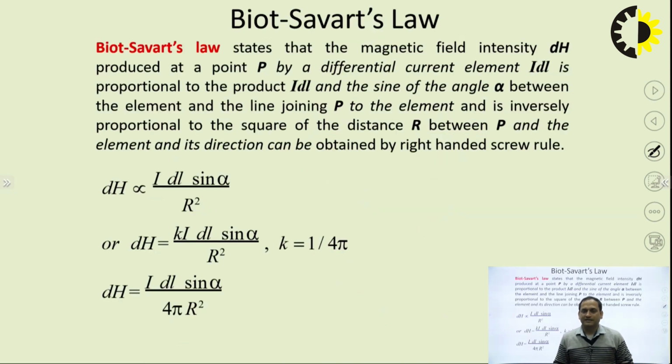Okay, so now let's start unit 3 in an efficient manner so that you can understand the things, or the crux of it. First is the analogy in the magnetic field as compared to the electric field. In the electric field we have the general law, that is Coulomb's law. An analogy here in the magnetic field, we have the Biot-Savart's law. So, what it says is that DH means the magnetic field at some point due to the line current.